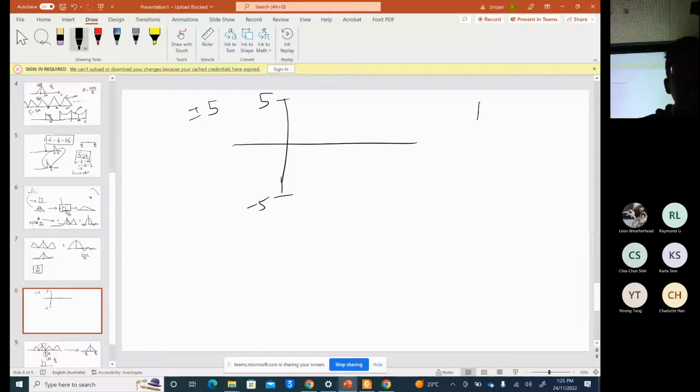Let's say B is equal to 2, then how many points can you have? 2 to the B points, that is 4. So you divide this into 4 divisions. This is the first quantization level, the second, third and fourth quantization level.